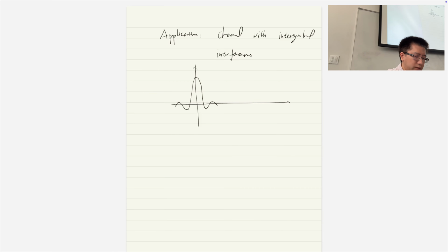This is the frequency domain, so we have f here. But this is just a rectangle. If we apply a phase shift in the time domain, multiplying by e to the power of j whatever, then in the frequency domain that will be a frequency shift. Very good.